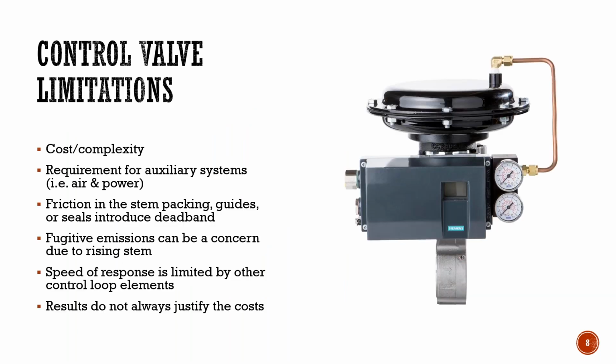What are the limitations? Well, you can do all that neat stuff with it, but as a result, there's added cost and complexity because you're not only talking about the control valve itself, but all the elements that are part of the control loop. There's a requirement for auxiliary systems. You need air, you may need electricity.